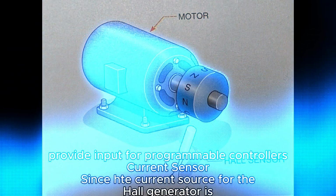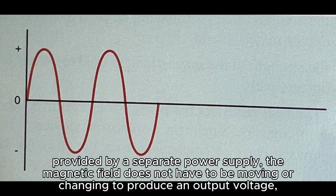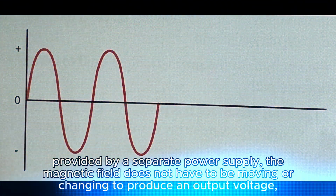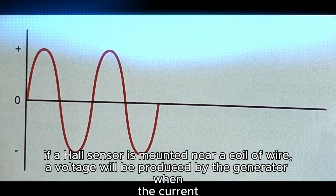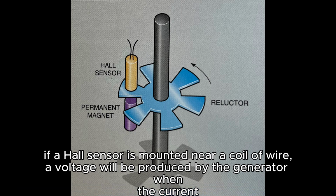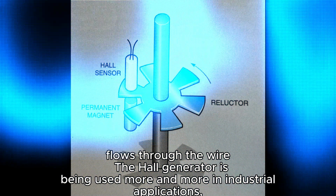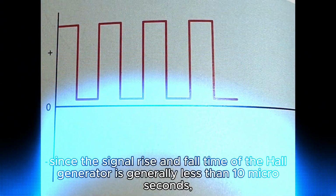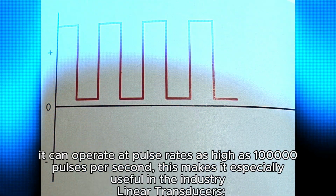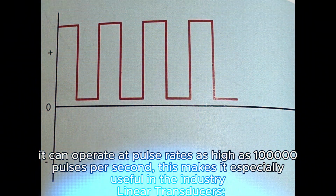Current sensor. Since the current source for the Hall generator is provided by a separate power supply, the magnetic field does not have to be moving or changing to produce an output voltage. If a Hall sensor is mounted near a coil of wire, a voltage will be produced by the generator when current flows through the wire. The Hall generator is being used more and more in industrial applications. Since the signal rise and fall time of the Hall generator is generally less than 10 microseconds, it can operate at pulse rates as high as 100,000 pulses per second. This makes it especially useful in industrial applications.